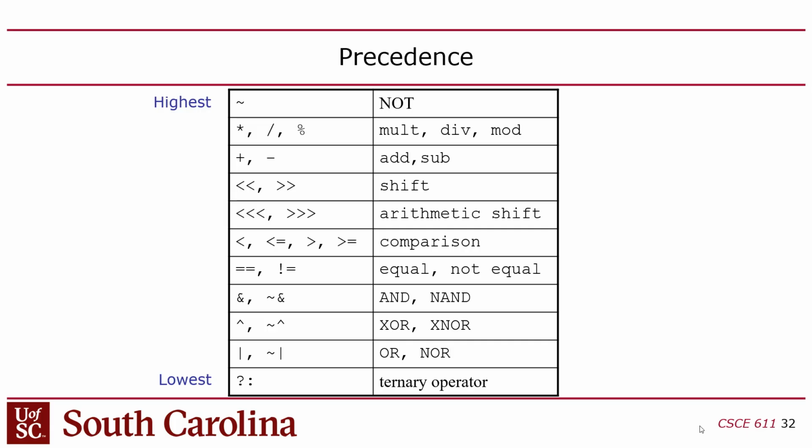If you're making hardware that you intend to synthesize, if you're making hardware that's supposed to be real hardware, it can only compare 0 and 1. It can only compare defined values. But remember that when you simulate this stuff, you can also have z's and x's, right? So if you have an equals equals and either side of that equals equals is an x or a z, then the entire expression is going to be x, right?